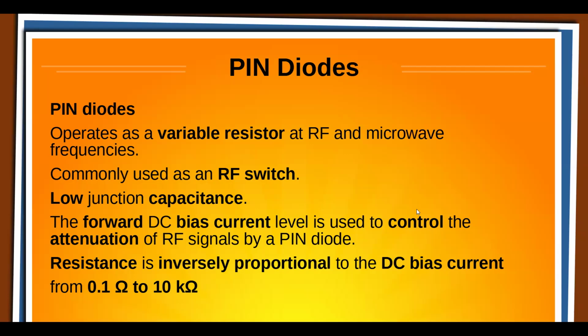They use these as essentially voltage controlled resistors in usually RF and microwave circuits. And you can also use it as a switch. A lot of times they will use pin diodes on each end of a filter circuit so that you can switch bandpass or low pass filters in by controlling the voltage on the pin diodes that make them act like switches.